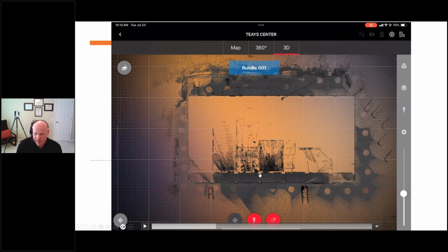Another thing to keep in mind with refracted data is that anything with low intensity, Register 360 Plus does a good job of weighting the use of cloud to cloud data. If it's low intensity, it de-weights it for the solution. But keep in mind that if there's a scan on this wall refracted from this angle and then also from this angle, now you have two walls that are maybe 3-4 millimeters refracted different, but both a plane. And that might be important if you're in an area where you're fighting for good registration features.